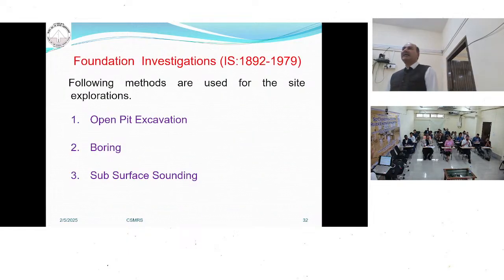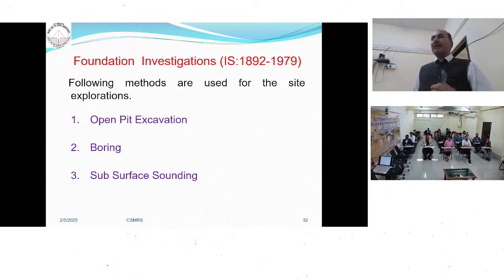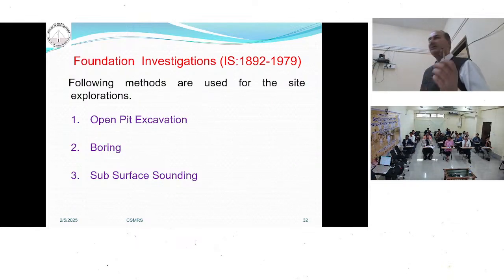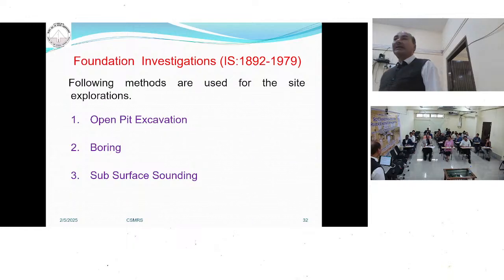So, how do we carry out the foundation investigation? Depending upon your structure, your project. Suppose it is a canal project, then you don't require to go up to the bedrock. You can carry out the foundation investigation up to 4 to 5 meters. That is more than sufficient. So, depending upon the project, you decide which kind of investigation you carry out. There are three kinds of investigation. One is the open pit excavation, second is boring, third is the subsurface sounding.